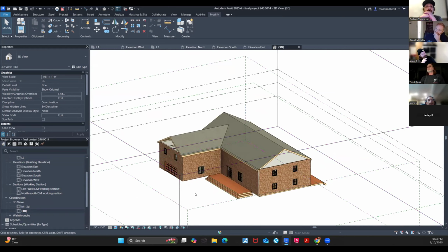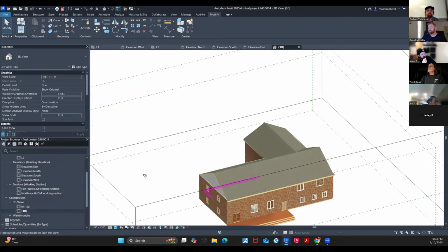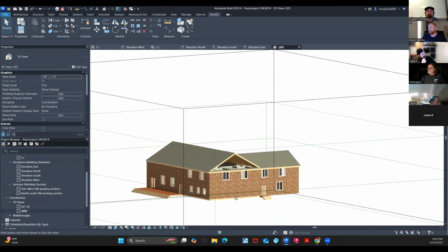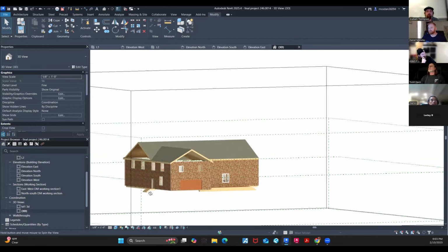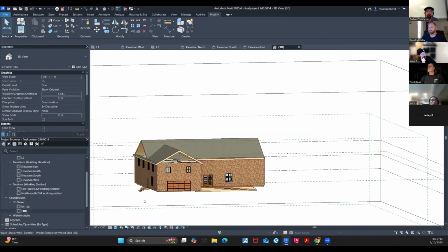But ultimately you got what we needed to, which was we drew those reference planes. So now we could draw a roof based off of that. We extruded that roof out in a flat roof and a pitched roof at a 30-degree pitch. Yeah, that looks way better. And then we took both of those and used the join tool and we were able to join those roofs together, right? And now it's one entity.